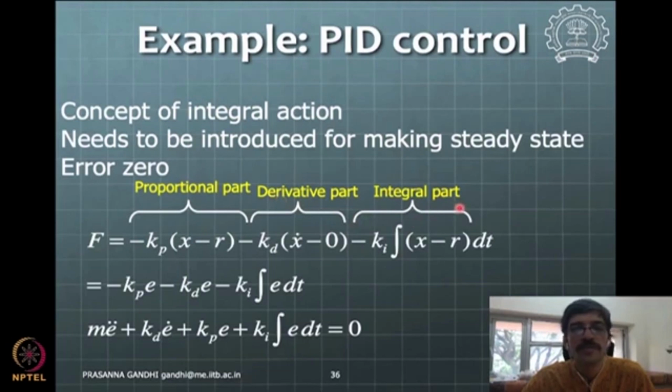You have seen in your simulation of the single link attached to a motor, that when you try to oscillate this pendulum, it doesn't come to the vertical position because of the friction. The friction is not allowing it to settle into the desired position. So this friction is causing a steady state error in the system.